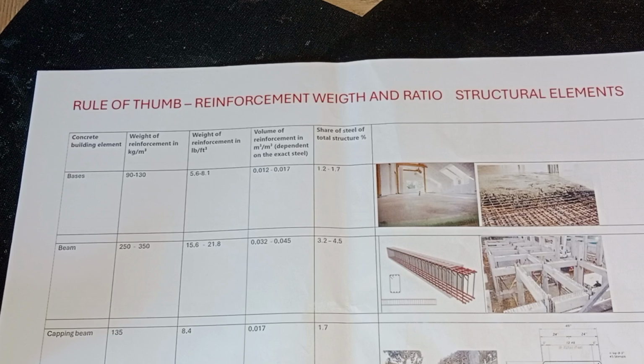they can reduce this. Here are just general recommendations for the reinforcement ratio and weight of the reinforcement in concrete volume for different types of structural elements, but always remember you need to follow the minimum and maximum range for each element in the applied reinforcement ratio. And also one more point, in some cases you may have required reinforcement less than the minimum reinforcement ratio in the applied code. Let's say, if you have very low load value, but anyway you have to provide the minimum reinforcement ratio even if you don't need that.